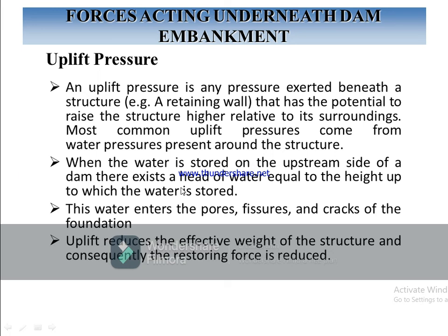When water is stored on the upstream side of a dam, there exists a head of water equal to the height to which the water is stored. This water enters the pores, fissures and cracks of the foundations. Uplift reduces the effective weight of the structure, and consequently the restoring force is reduced.